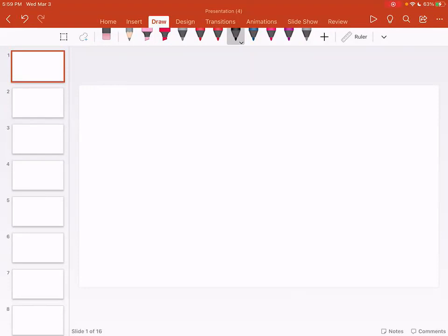Okay, welcome to EGR445. In today's class, we will solve some spur gear problems, and then we will talk about how we can extend what we learned in last class to design helical gears. Now, please understand, the design procedure for helical gears is similar to spur gears. So, for the purposes of design, we will convert a helical gear into an equivalent spur gear and then perform the analysis. But recognize the shaft design for spur gear and helical gear will be slightly different.